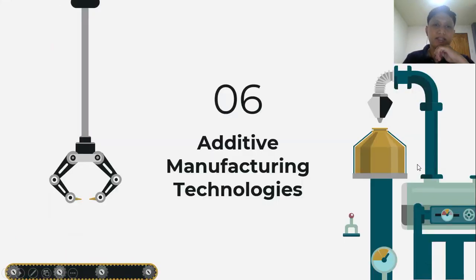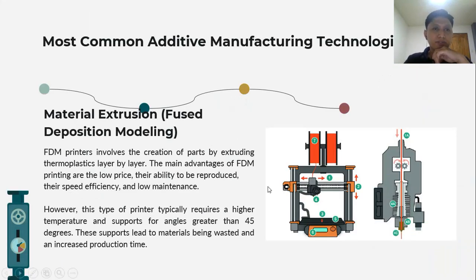Lastly, the additive manufacturing technologies. Most common additive manufacturing technologies. First is the material extrusion, or FDM. Fused deposition modeling printers involve the creation of parts by extruding thermoplastics layer by layer.